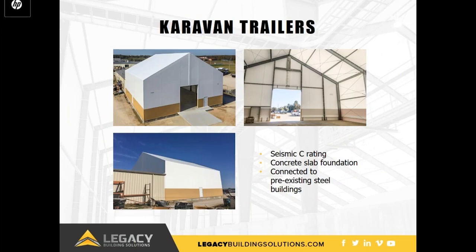This is a 60 by 60 manufacturing building with a seismic design category of C. It uses a concrete slab foundation to account for the soil conditions. The sidewalls are 22 feet in height to create more space for equipment and manufacturing inside. You can see in the background that this building is connected to a steel building that was already in place. We'll talk a little more about how tension membrane buildings connect to other building types later.